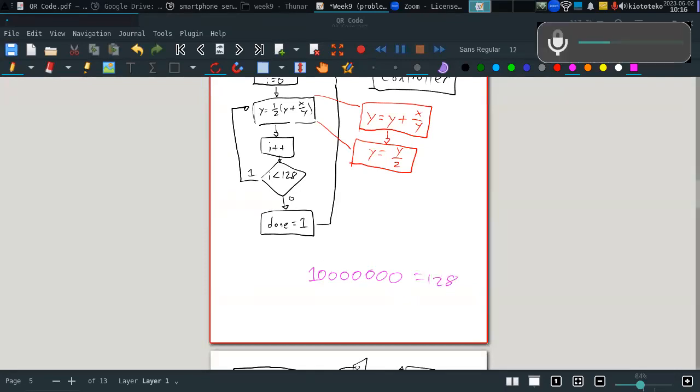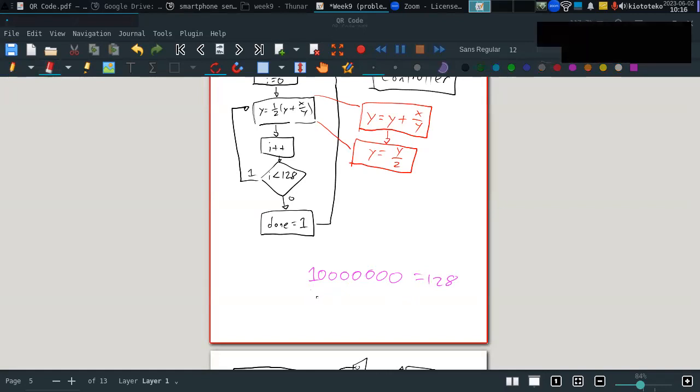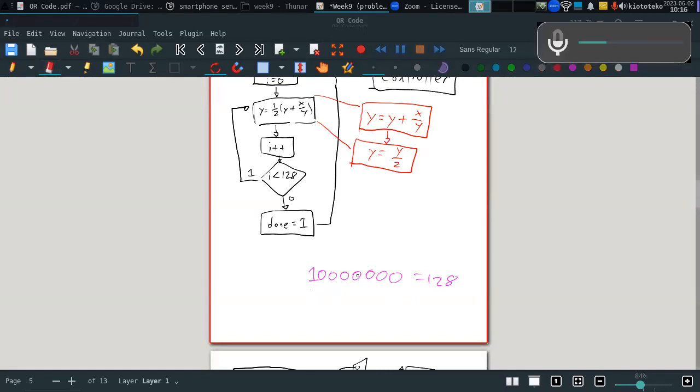If our value is lower than this, then we will have a 0 here, no? If it's greater than that, 128 or greater, that's our condition, no? As you were saying, yeah, we can right shift this value. Well, why not just separate this? These bits are comprised of wires, no? So we can just check this last wire to see if it's a 1, and if it's a 1, that's it, no? So that's as simple as it gets.